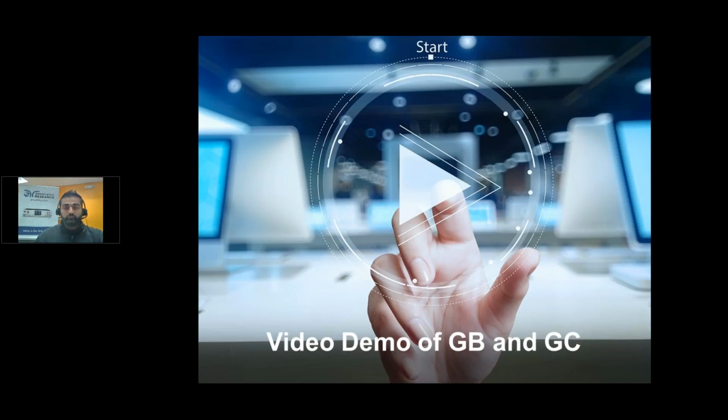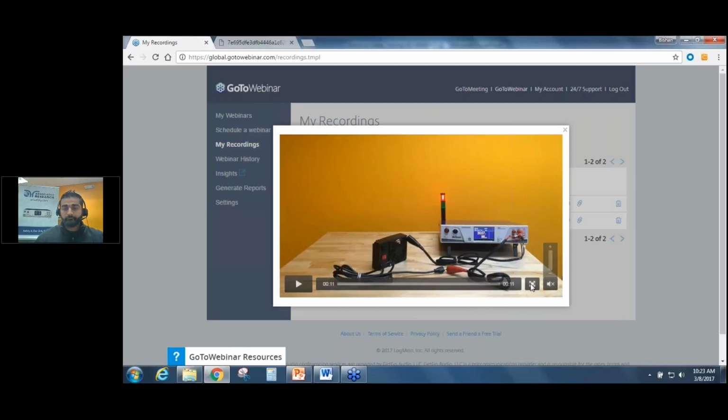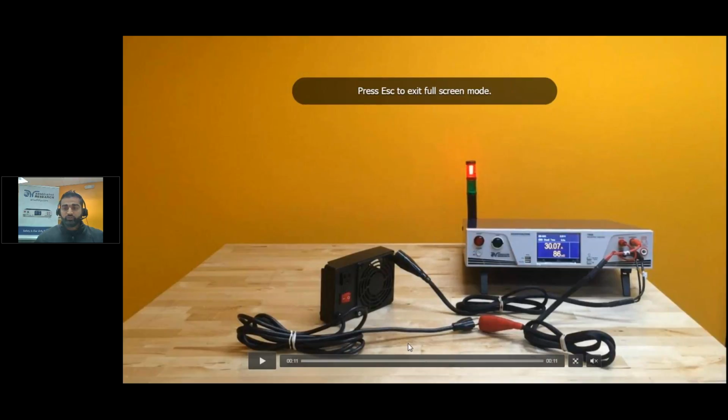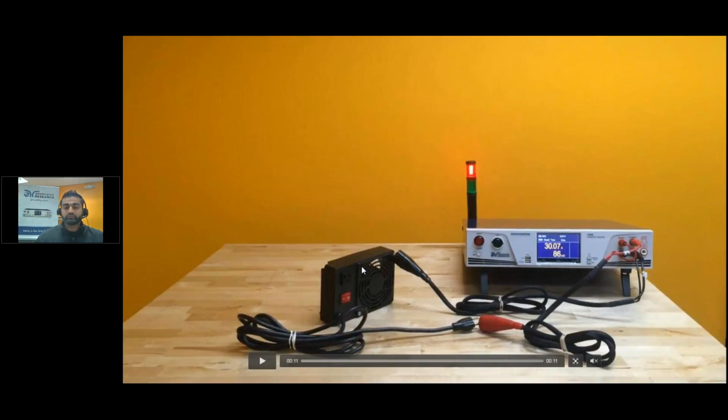So, all right. We do have a video, and in this video we're going to be showing you using our Hyper Ultra to perform a ground bond test and a ground continuity test. And let me go ahead and bring that video up here real quick. So you could see in this video that we have our product connected, it's a fan. Even though the fan is plastic, it has these metal screws, so that's a metal accessible part. It is a class 1 product, so it has a ground pin here due to the fact that it has this metal accessible part. And you see the tester on the right here is our Hyper Ultra. So I'm going to play this video and then talk about the results in a second.